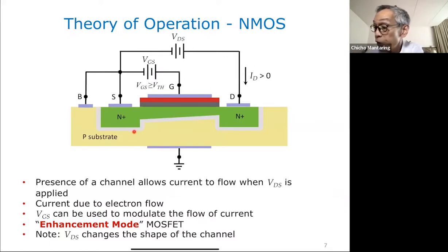Your depletion region now exists here, no, all throughout this area. Because now, all throughout this area, I will either have a high reverse bias between my N and my P. So we're talking here about my N region. This is my N region, the channel or my drain and source, and my P. Here I will have a high reverse bias. Here I will have it unbiased. And then as I travel from the right to the left, okay, the amount of reverse bias between the N and the P